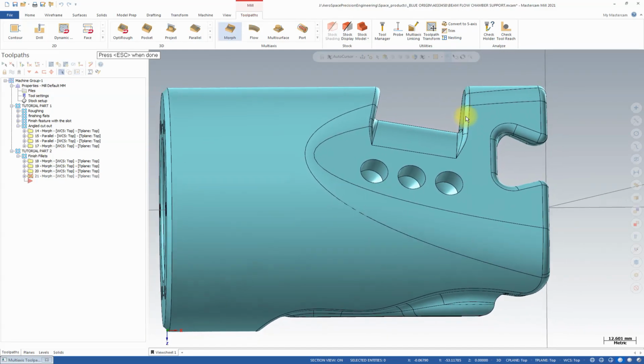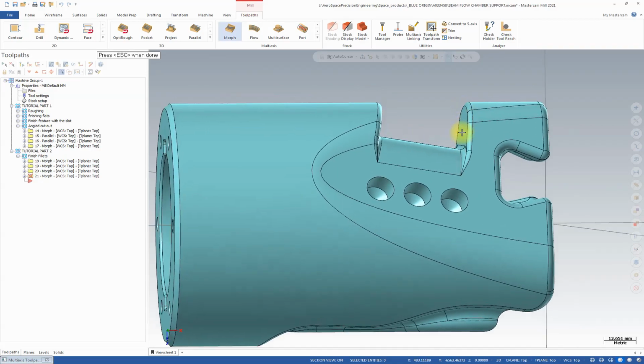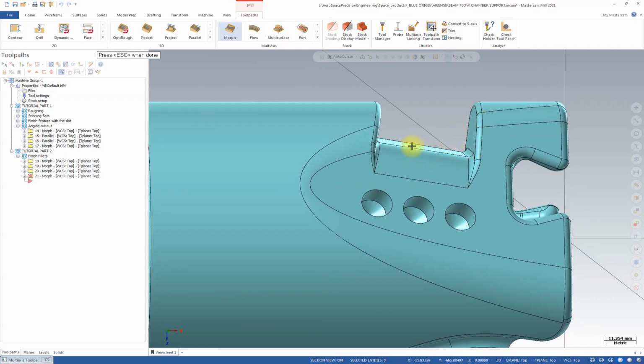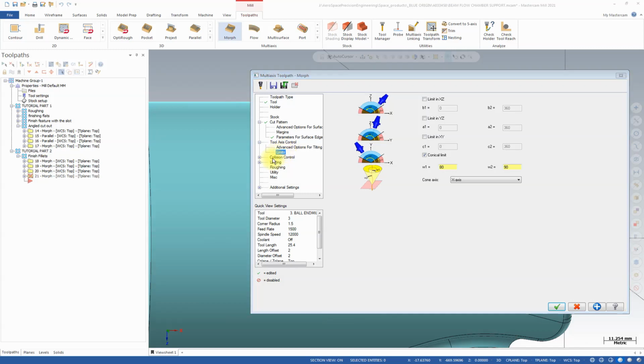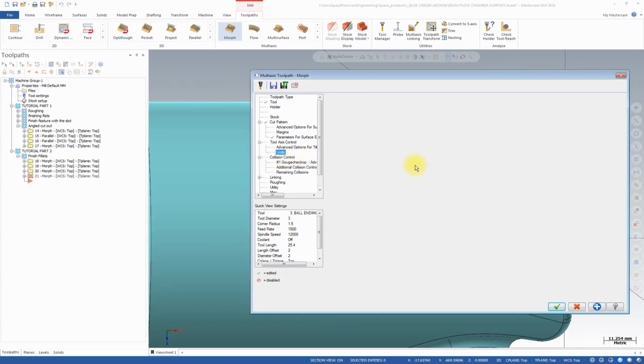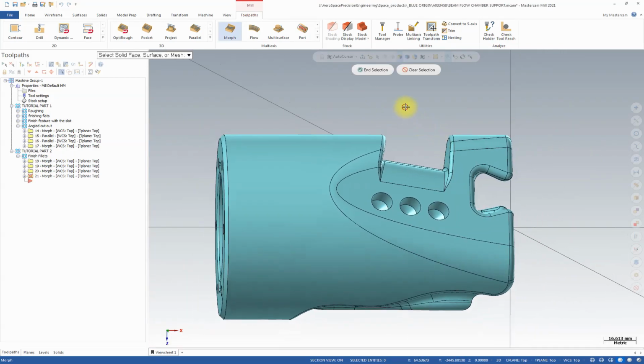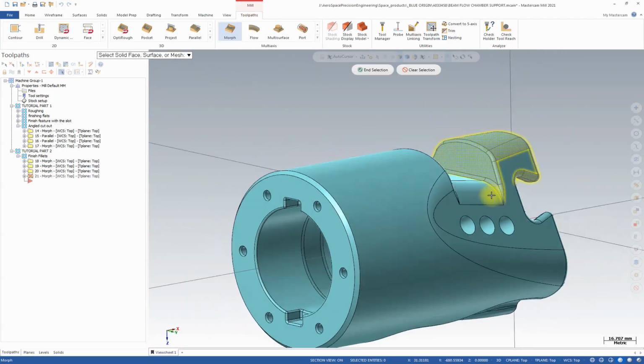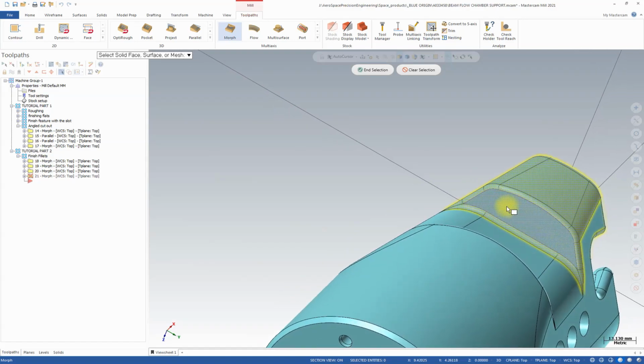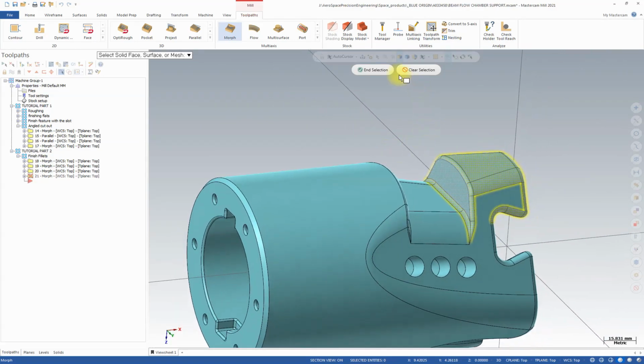That shouldn't be my tool hitting that face, but just in case, we can add some collision control, and let's tilt the tool to the side if we hit anything from here. So anything on that face, we will tilt the tool.